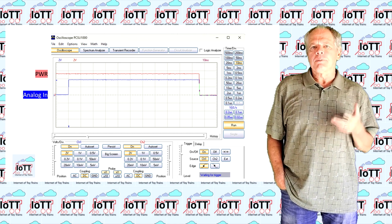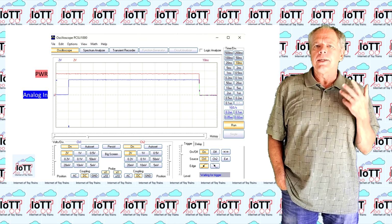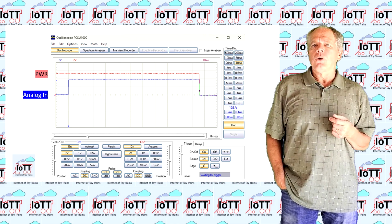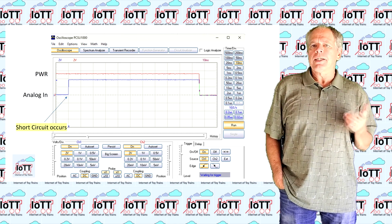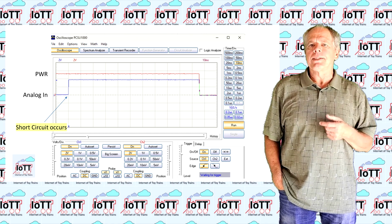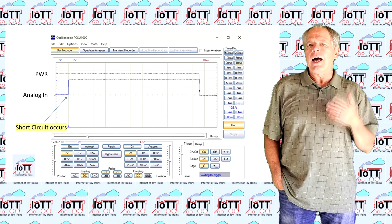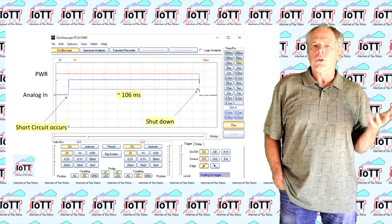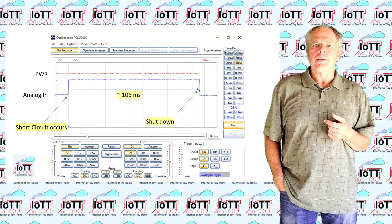The red line is the power pin that enables the H-bridge. The blue line shows the analog input. If a short circuit occurs, the analog input goes up as the current increases. If analog is still high about 100 milliseconds later, the power line goes low to shut down the track output.